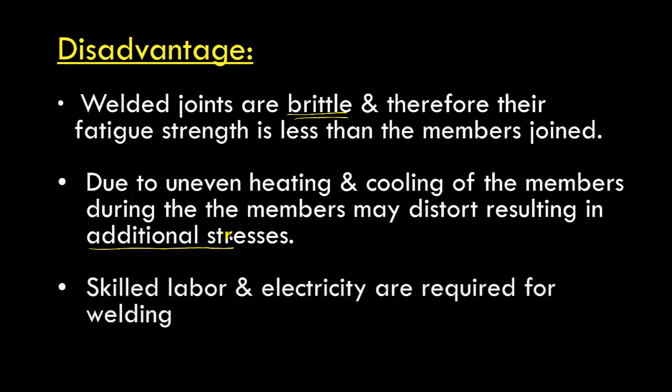And for a welding connection, you require very skilled labor. There are some people who do a diploma, and then they are called welders. These people are the only ones allowed to do welding. But bolting does not require so much skilled labor. Semi-skilled or unskilled workers can also do the bolting process, but for welding you require highly skilled labor, and it also requires electricity. For this reason you can't do welding in remote areas where you don't have electricity. You need continuous electricity for welding.